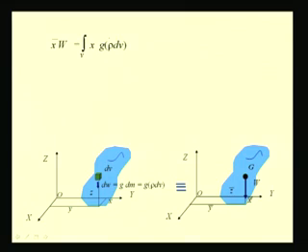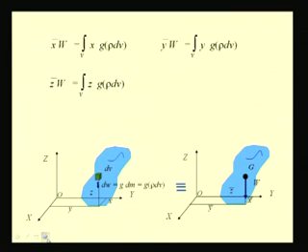Similarly, we can sum the moments with respect to the other axes, that is say with respect to OX, in which case the moment arm is y bar, and if we take the axis OZ, then we have this moment arm of z bar. So, we can write these additional equations, that is y bar W equal to integral V y times g rho dV.